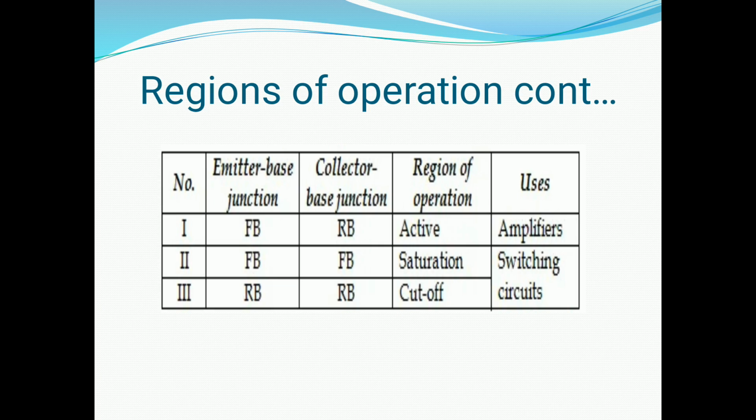Last case, when the emitter base junction is reverse bias and collector base junction is also reverse bias, the transistor remains in cutoff region and it corresponds to logical off or open circuit.